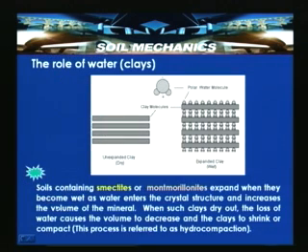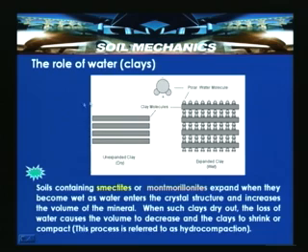Contrary to this, the behavior is entirely different when you supply water to a clay soil, or a soil which has smectite and montmorillonite minerals. When water is supplied, the soil tries to keep it and tries to swell or expand. That behavior is shown in this slide, where this is an unexpanded clay and this is expanded clay with pore water molecules. So, soils containing smectites or montmorillonites expand when they become wet, as water enters the crystal structure and increases the volume of the material.